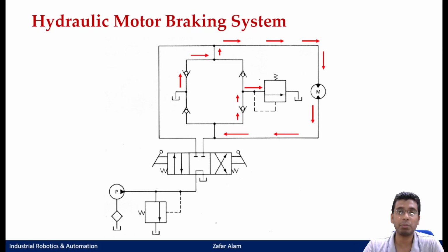Otherwise, if you suddenly apply this center position and put your motors to a halt, and you do not have this type of braking system in place, then this would lead to catastrophic failure of your motors if a very high amount of load is coupled to them. And of course, in a hydraulic circuit, you generally have a very high amount of load because of the pretty high operating range that these circuits generally operate at.